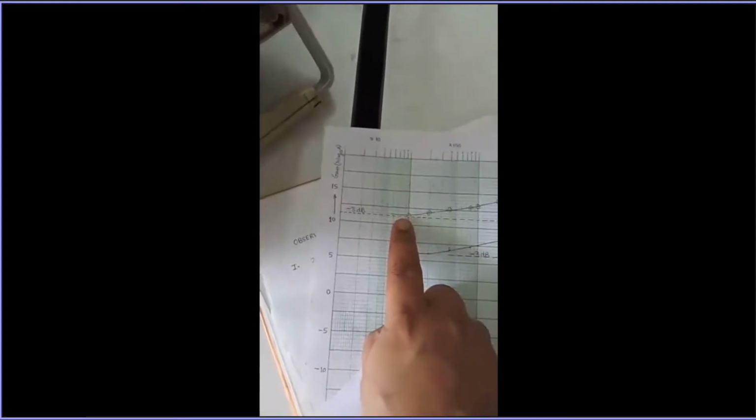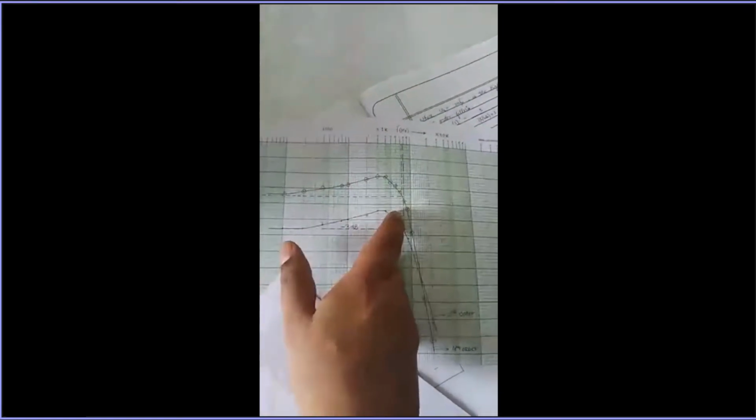So you can see the plot. I guess it is visible. The second order and the fourth order you can easily see, right? So you will have to make the plot, and then draw a minus 3 dB line. Minus 3 dB means what? 3 dB below the peak value. This is the peak value. So 3 dB below the peak value will give you the bandwidth for the fourth order and for the second order respectively, right? So likewise you have to draw.